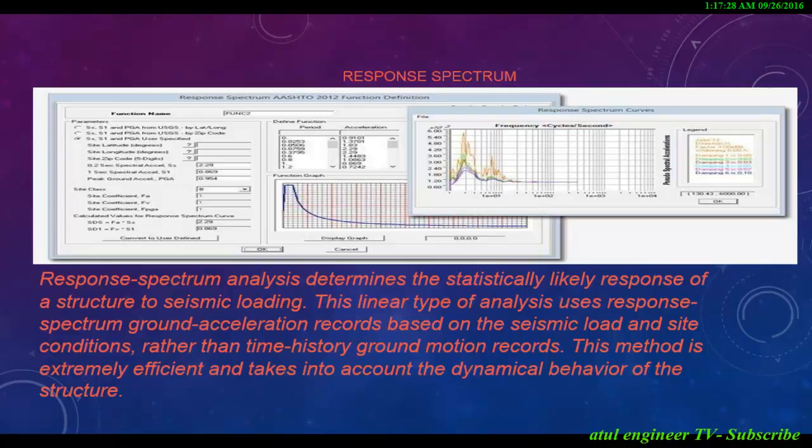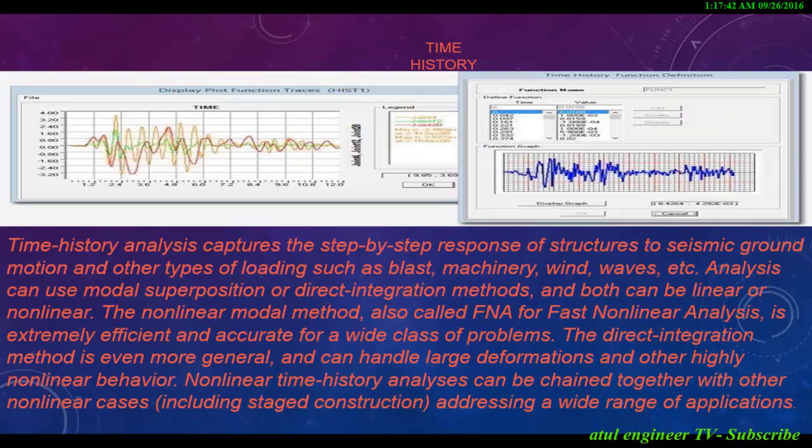Response spectrum. Response spectrum analysis determines the statistically likely response of a structure to seismic loading. This linear type of analysis uses response spectrum ground acceleration records based on the seismic load and site conditions, rather than time history ground motion records. This method is extremely efficient and takes into account the dynamic behavior of the structure.